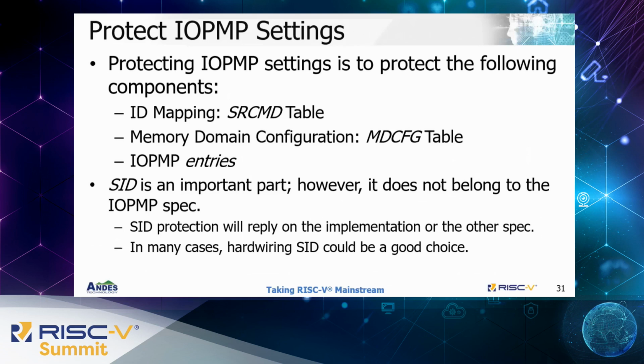The MD CFG table defines which IOPMP entries belong to an MD. The relation should be able to be locked. An IOPMP entry contains a region and a permission. This content should also be able to be locked. We will not mention the SID protection subsequently.